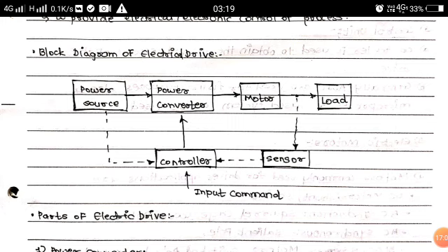So what can be done? Motor currents could be sensed, and from that the flux in the machine can be calculated, or in other words, it can be estimated, or in other words again, it can be observed. So observers you might have studied in control systems. Those observers are doing such a function. It is some mathematical formula and some program in the controller, which is used to calculate the required quantity. So some quantity has to be sensed or estimated or observed. Then that quantity, that actual output, is given to the controller.